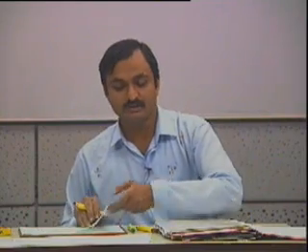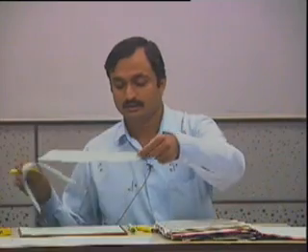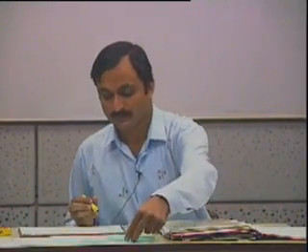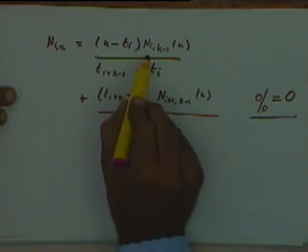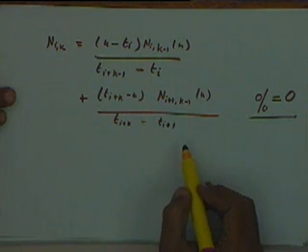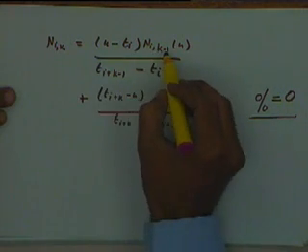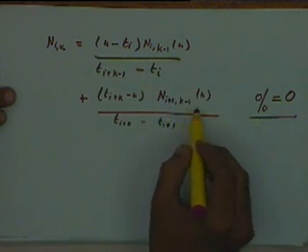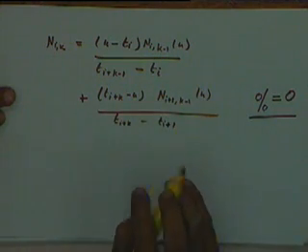And for defining nik for higher values of k, that is when k is greater than 1, we said we will use a recursive definition, and the B-spline curve was given by this expression, where nik is u minus ti times ni k minus 1 divided by this expression, and so on. Essentially nik depends on ni k minus 1 and ni plus 1 k minus 1. So this is a recursive definition we had given yesterday.